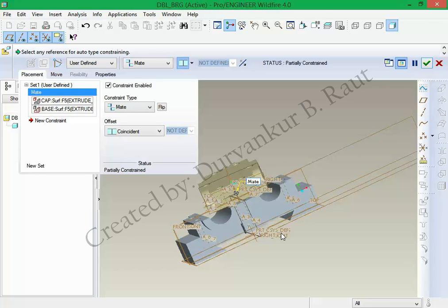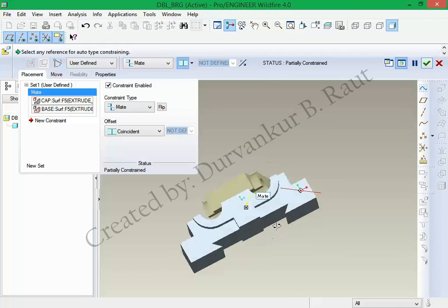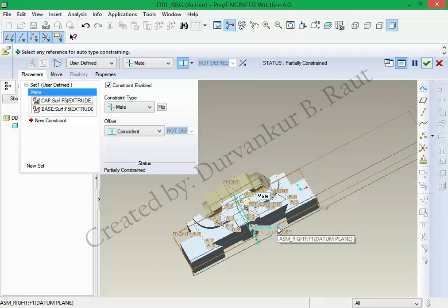If you want to rotate all assembly at once, then your earlier mouse buttons are okay. You can use them. Like if you just click on the middle mouse button, everything will rotate. Okay. If you just want to rotate the part which you are assembling, then you need to press Control and Alt button simultaneously, and then click on middle mouse buttons. ठीक है? जरा सा complex है. Control Alt simultaneously, and then middle mouse button. That will rotate only the part which you are assembling currently.